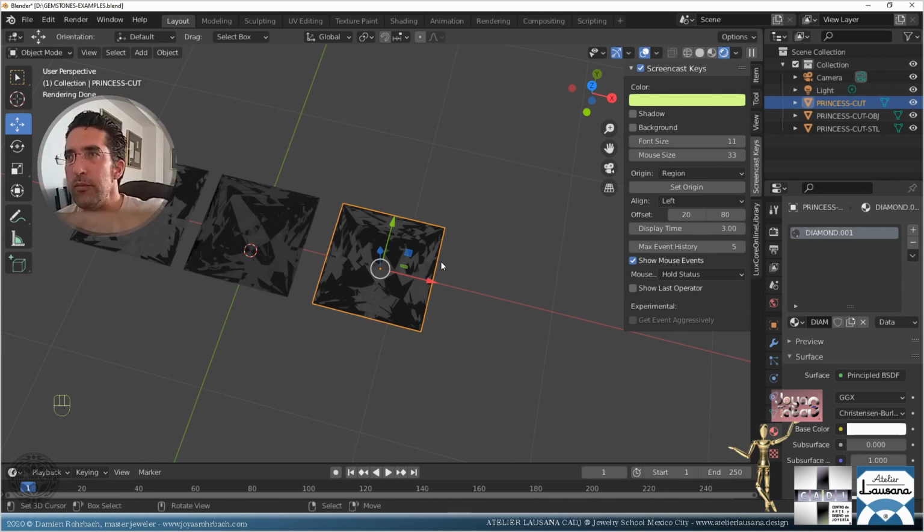Okay, and it's all inside Blender, and you're going to append with already the materials. So you can create another scene, make the materials you use the most, and then append your gemstone, your rings, shanks, designs, and all into a new scene, and it's going to be exactly the same geometry as the original. So know that exporting, even in object file, is going to change slightly the geometry. STL changes it more. But when you append, the file is taken from the original and it's somehow linked.